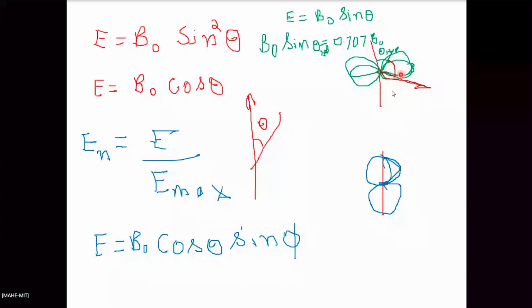Sir, is it the angle between two consecutive half power angles? Yes, same thing. At 45 degrees you have one half power angle, and at 135 degrees you have the other. In between, on either side of the maxima, are the half power points. That is the half power beam width.